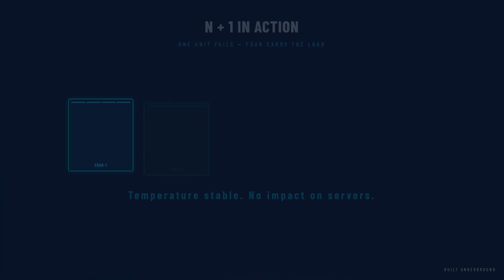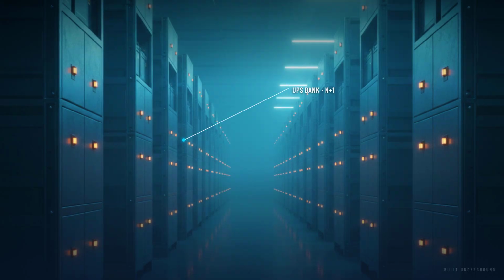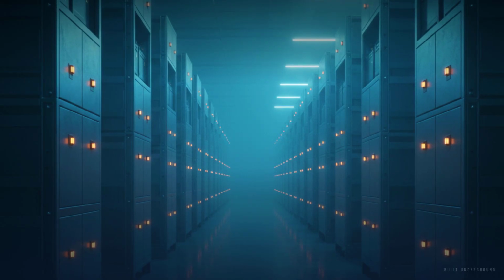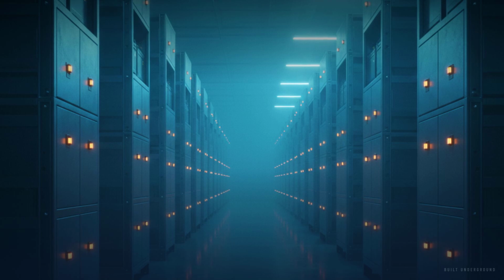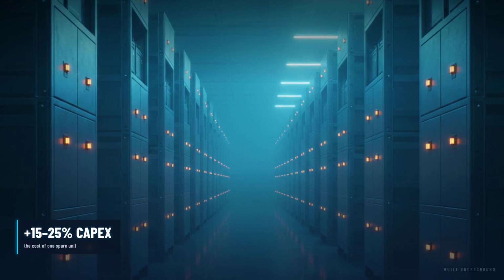The same principle applies to power. If the facility needs 3 UPS modules to support the IT load, an N+1 design installs 4. One can fail or be taken offline for maintenance without affecting operations. N+1 is efficient. It provides protection against a single component failure with minimal additional capital cost, typically 15 to 25% more than the base system.